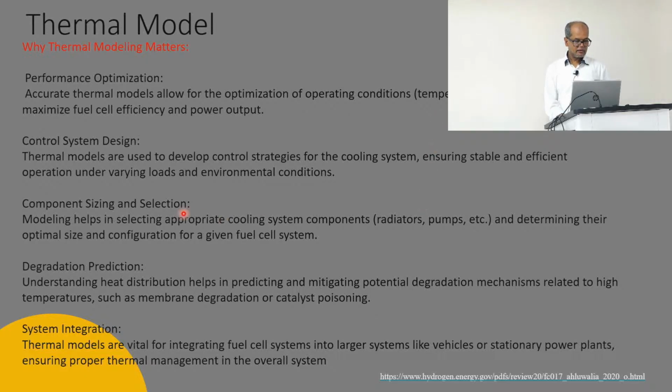And also the component sizing and selection for your cooling system, like the radiator and pump. If you want to determine exactly what size of pump and what size of radiator you need for a given fuel cell system, then you need the thermal model. And another thing, if you want to predict the degradation, because like the battery or fuel cell, with respect to time its capacity will deteriorate.